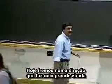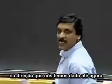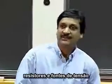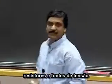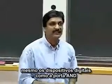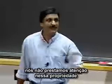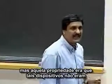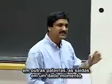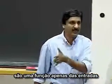Today, we move in the direction that takes a big turn from the direction we've been going in so far. All the devices we had up to now, resistors and voltage sources and even your digital devices like the AND gate or the inverter and so on, had a very specific property. We didn't dwell on that property, but that property was that these were not what are called memory devices. In other words, the outputs at any given time are a function of the inputs alone.